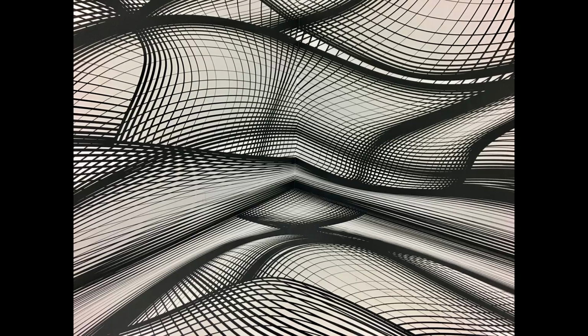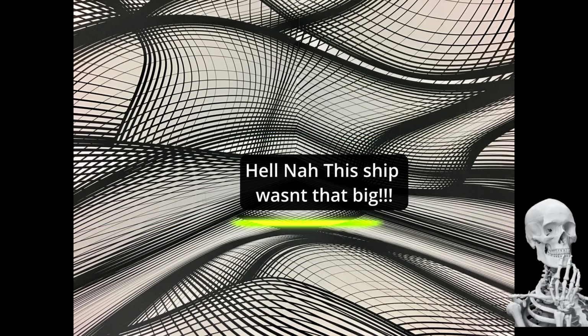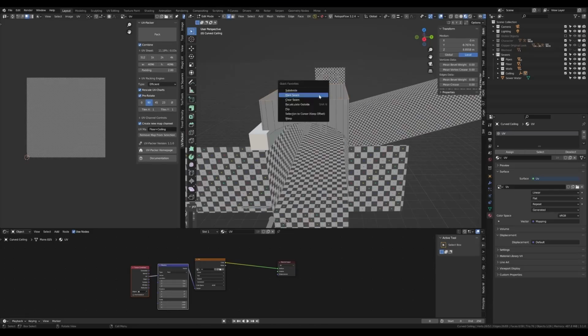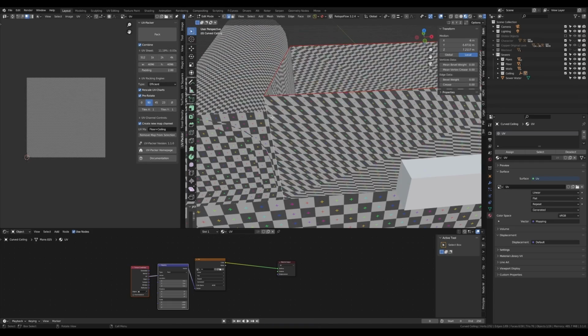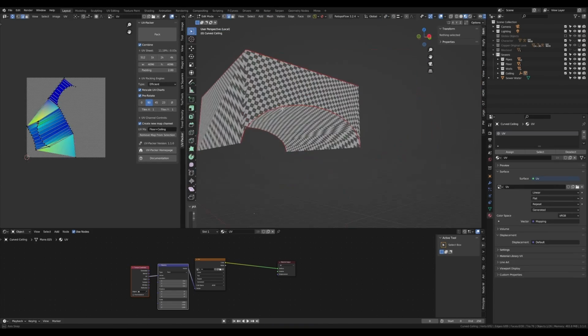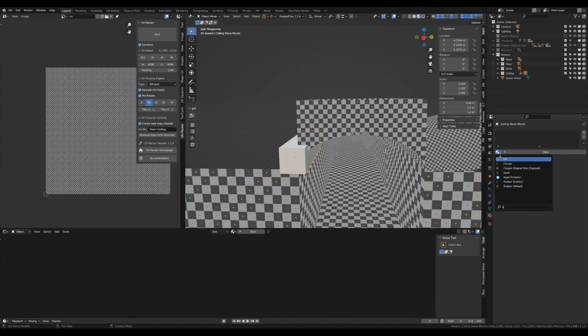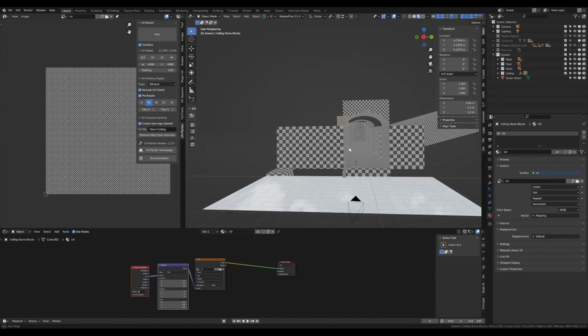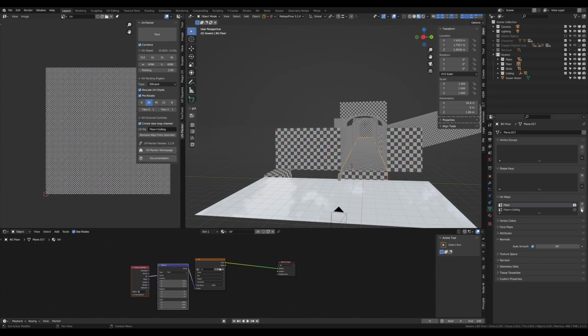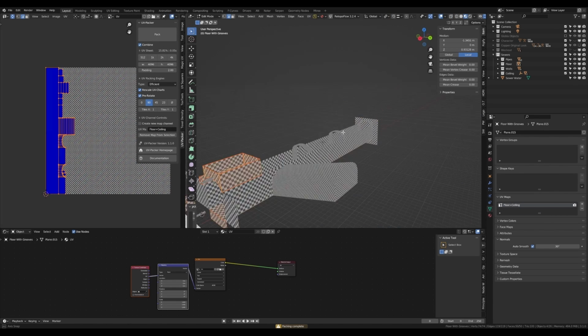And I'll know if I'm headed in the right direction if the squares in my textures look like squares. You tend to forget what squares look like when you see this for hours on end as you sort this whole mess out. As I UV unwrap my object, you'll see me adding these red lines, which are called seams. These basically tell Blender where to cut the object as it flattens it. I mainly add these along the top and bottom of objects and along one of their sides, or wherever the faces take a sharp turn like a corner. And after doing this nightmare, we're left with this.